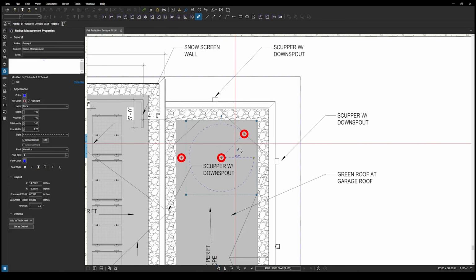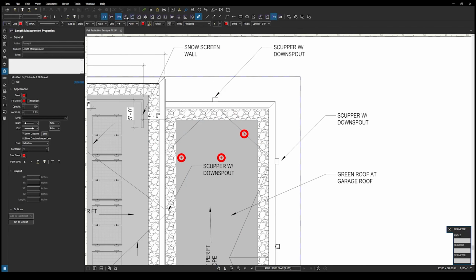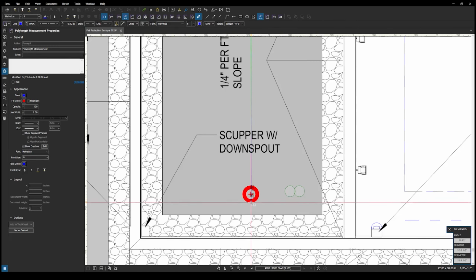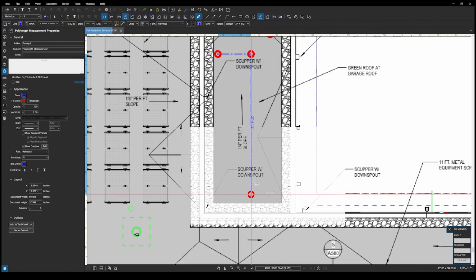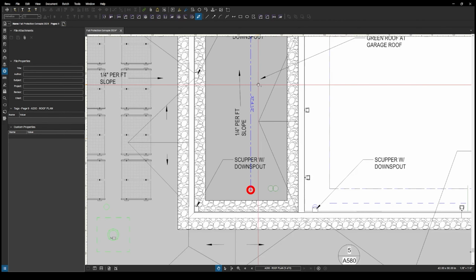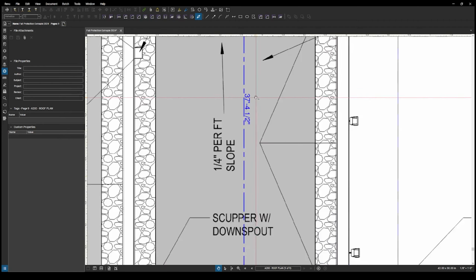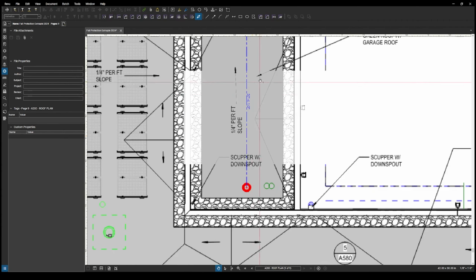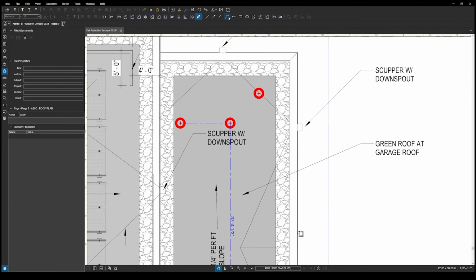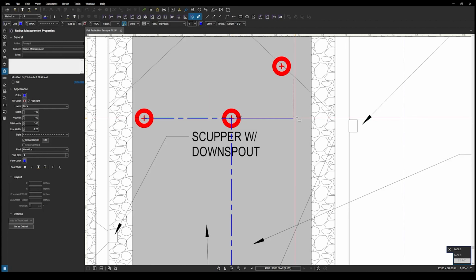We're going to add in an additional anchor here at the corner, which is within 6 feet, which is then going to allow the worker to detach from that double lanyard, attach with this anchor, then come back and detach here, and they can reach all this stuff here, and that's still within that area. But because they're attached to an independent anchor, we can place it much closer. So that's great. So it just needs to be within 6 feet of the closest anchor, because this anchor right here then falls within the fall hazard zone, which is 6 feet inward from the building edge.